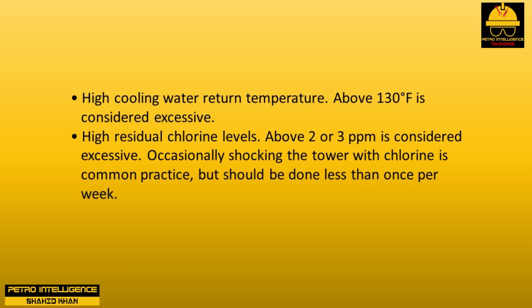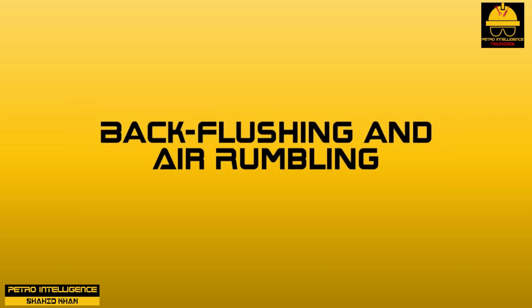The two things that will accelerate the rate of lignin loss from the wooden components of the cooling tower are high cooling water return temperature, above 130 degrees Fahrenheit being considered excessive, and high residual chlorine levels, above 2 or 3 ppm being considered excessive. Occasionally shocking the tower with chlorine is common practice but should be done less than once per week.